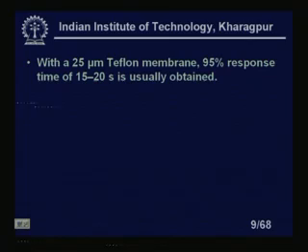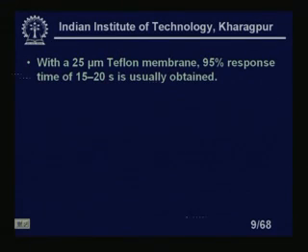With a 25 micron Teflon membrane, a 95% response time of 15 to 20 seconds is usually obtained, right. Response time means the time within 15 to 20 seconds, if you consider a step input, suppose a probe is inserted or there is a change in the concentration of dissolved oxygen or partial pressure of oxygen.